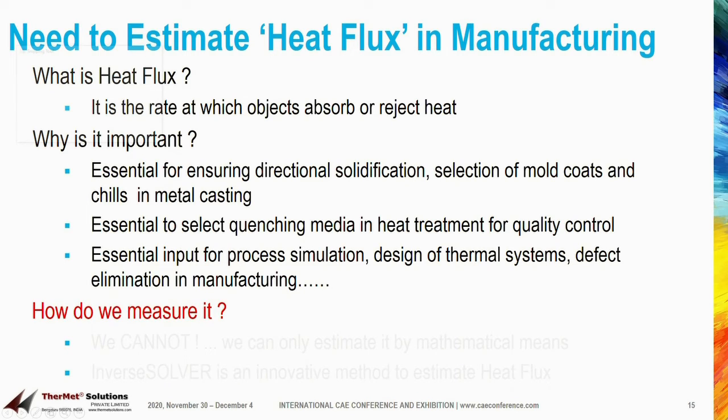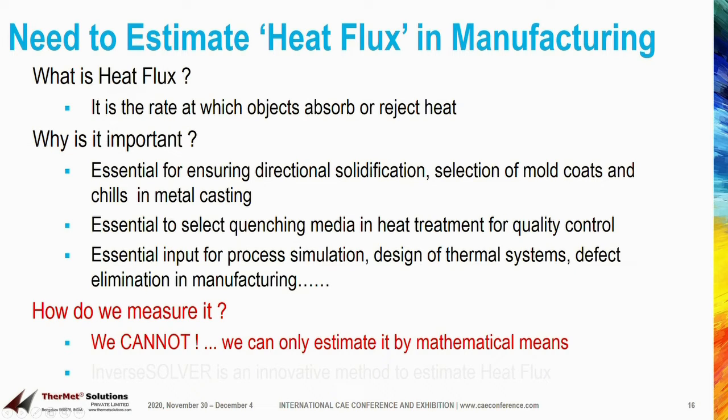How do we quantify or measure it? Though we have sensors for measuring heat flux, say in a furnace atmosphere by flux meters, we cannot measure the heat flux when the process is inaccessible, like between the mold and the casting at the mold metal interface, or when it is too complex for calculations like during quenching.